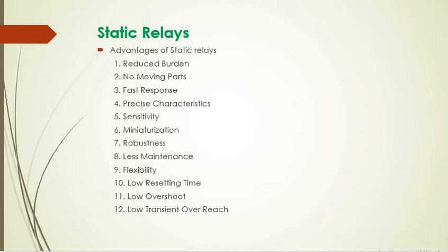A variety of functions like sensing of negative phase sequence component of current or voltage, filtering, harmonics, differentiation, integration, etc. can be performed with greater flexibility by static circuits, and hence these relays can match the requirements of protection more closely.